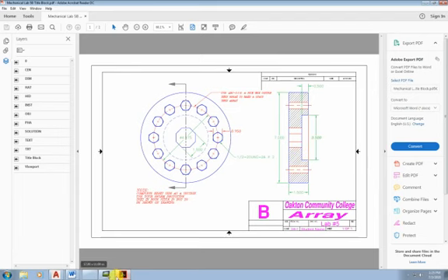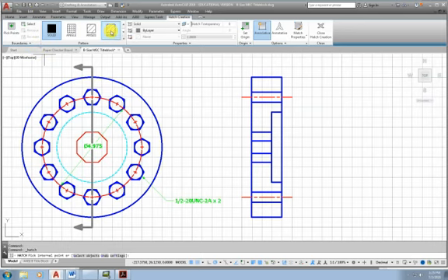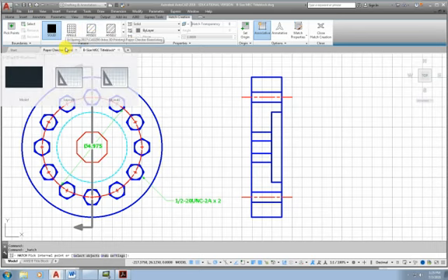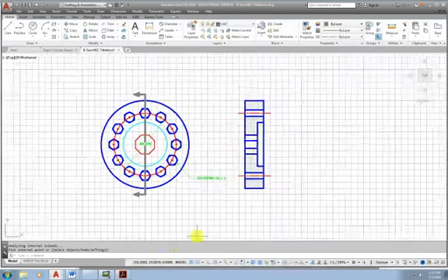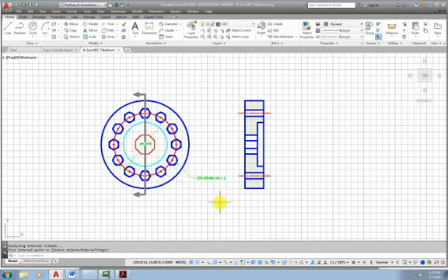It is not. And so when we look at the hatch patterns in AutoCAD, they relate to different material types. ANSI 131 would be American National Standards Institute 131, which basically goes into the type of steel it is and the carbon content. But for now, I'm just going to choose that as my pattern, and if I hover, it will detect the boundaries, and then I'll click, click, click, click, and close the hatch pattern. And that will apply that hatch pattern to the drawing.